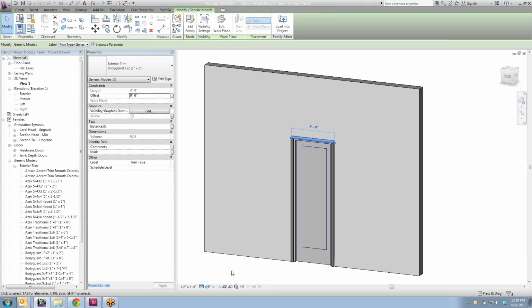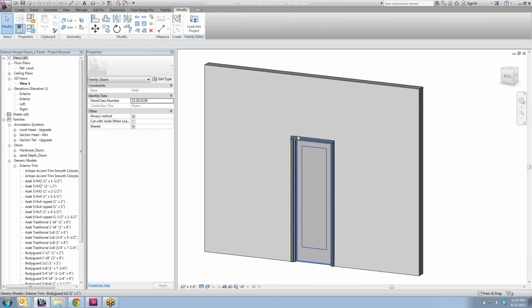So unfortunately, selecting the trim doesn't change the trim width parameter. You have to set the trim width parameter once you change the trim, as it controls the way that these corners line up.